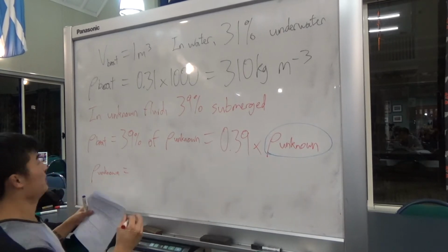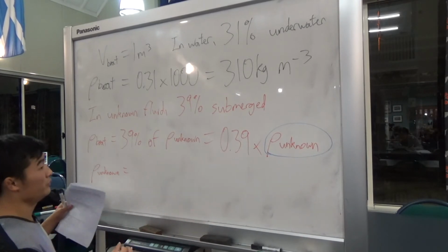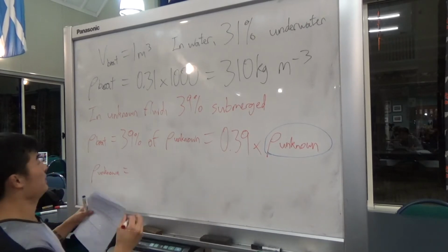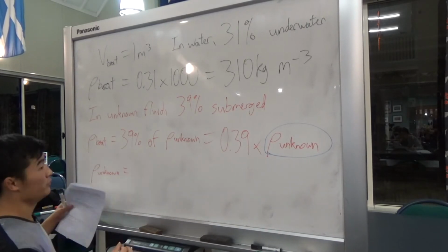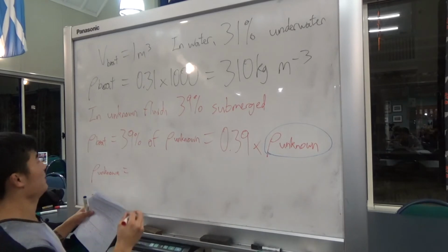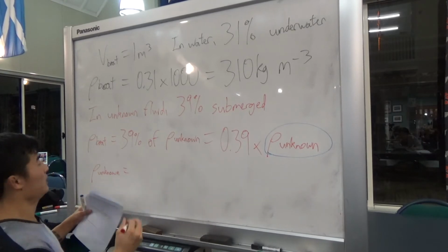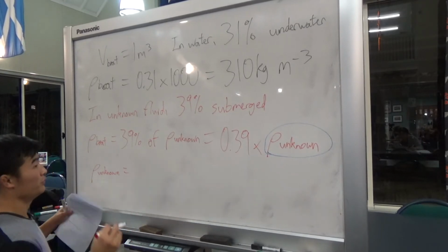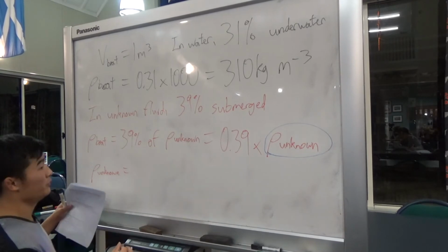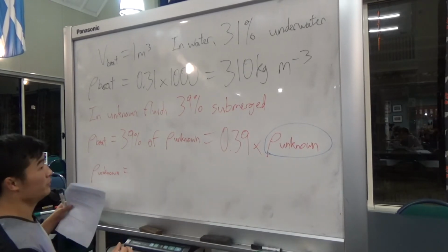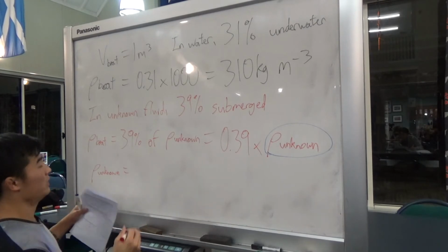What volume of fluid is discharged from the pipe in 500 seconds? So for this question, you'll know that flow rate is equal to volume over time, or the change in volume over time. And that's also equal to the cross-sectional area multiplied by the velocity. So here we can just use these two equations. So we'll get rid of the flow rate. So we have the change in volume over the time is equal to area times velocity.